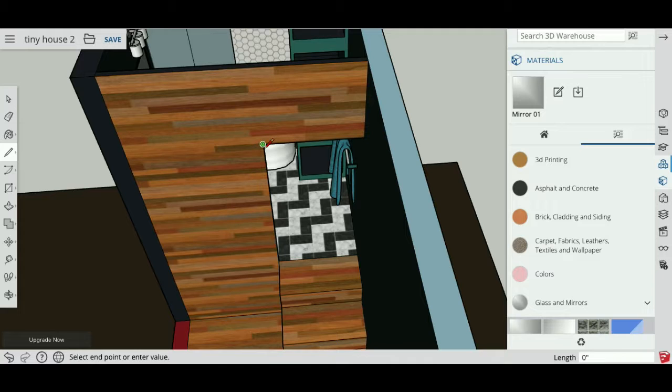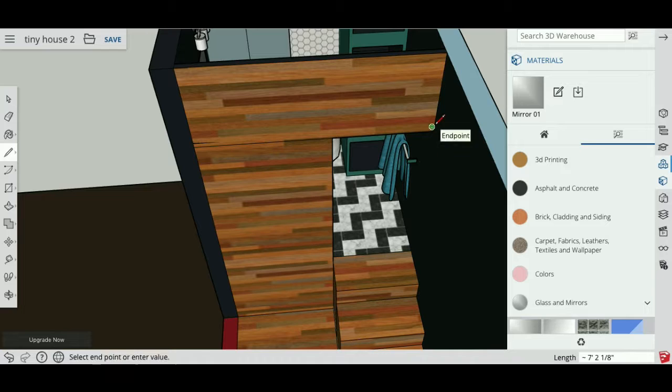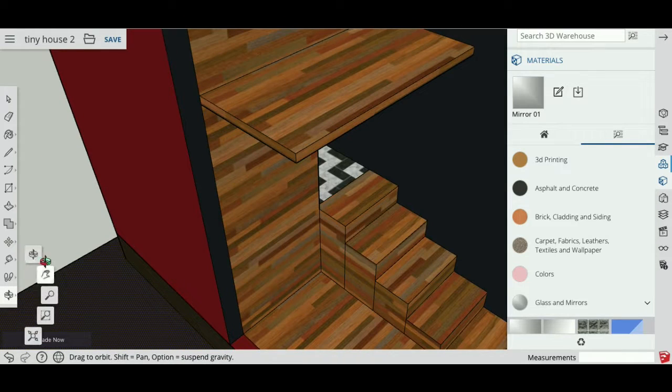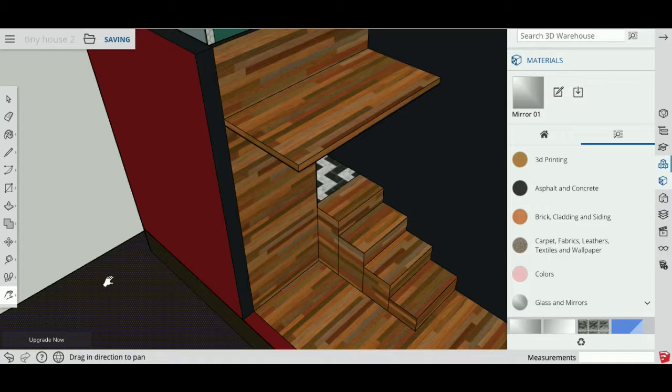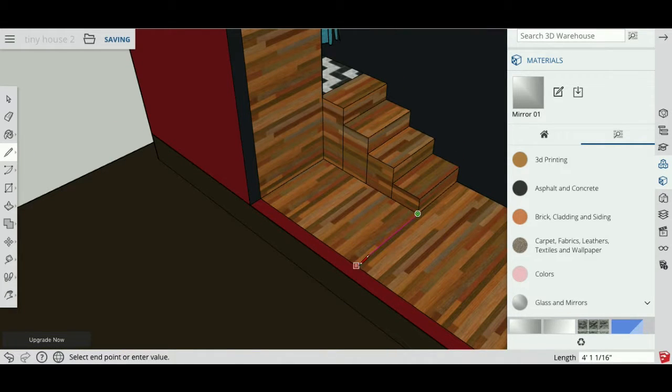So once I figured out what the height had to be, I realized because I was using stairs, I would need to make sure that there was room for somebody to walk through. So I just created a space that was shorter than the loft height needed to be. And I figured I could just make it a storage space. Or I can make it part of the laundry room here. Since somebody does need to walk up those stairs, you gotta make it at least 6 feet for me to walk up.